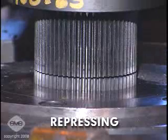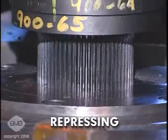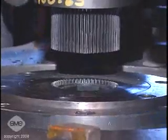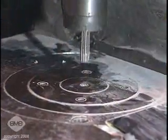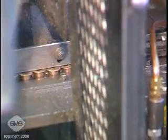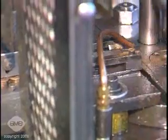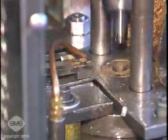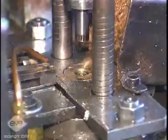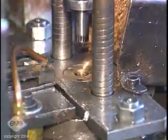Repressing is occasionally used when mechanical pressing and sintering do not yield sufficient density to meet the part's required performance. Repressing is also used to coin or size parts to close tolerances. Repressing, which can be done at room or elevated temperatures, usually requires additional tooling. The part may have to be annealed or softened first, or sinter annealed during sintering.